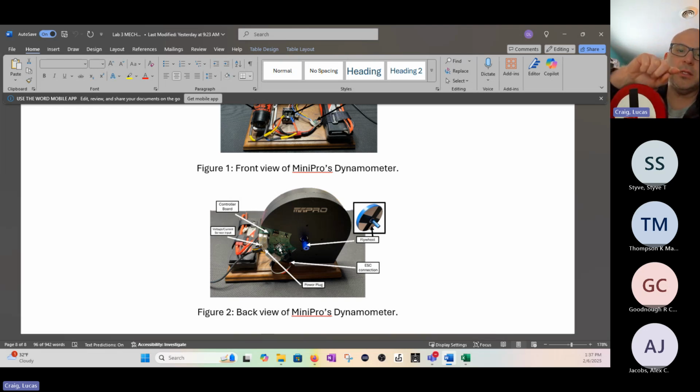That sensor will read a voltage of 0 when it's white, and then it will jump up to maybe 4 or 5 volts when it hits the black. So as this spins around, if you count the number of times it spikes up in say 1 second, you can convert that count into what we call RPMs. Once we know the RPMs, we can figure out other characteristics of that motor.